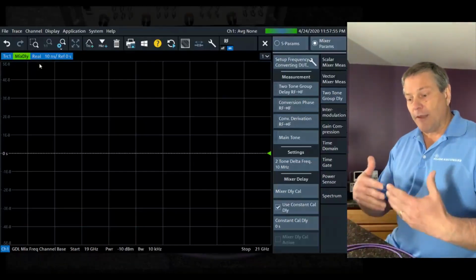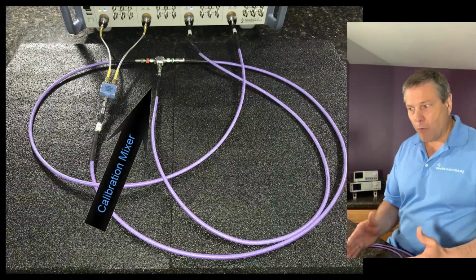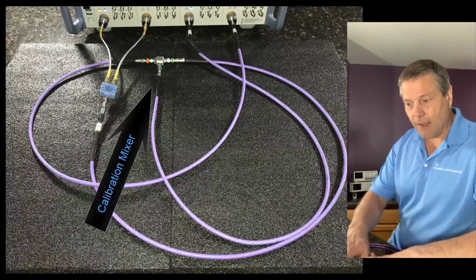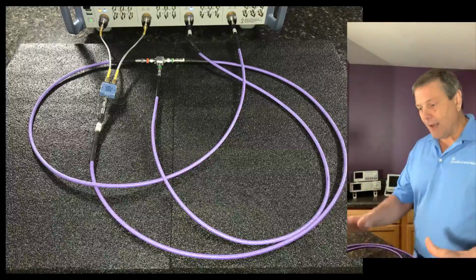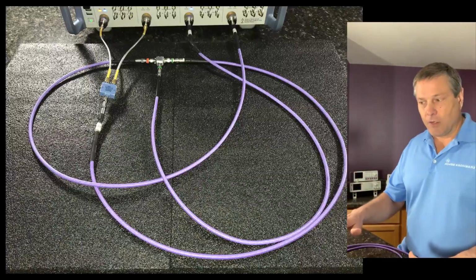I'm going to connect a characterized mixer to the setup, and then we're going to press calibrate in order to calibrate the channel so that we take out the effects of all the cables that are interconnecting between the network analyzer and the device under test. I've already set that up. It looks like this. Here's a picture, and this is all I need in order to do the calibration.